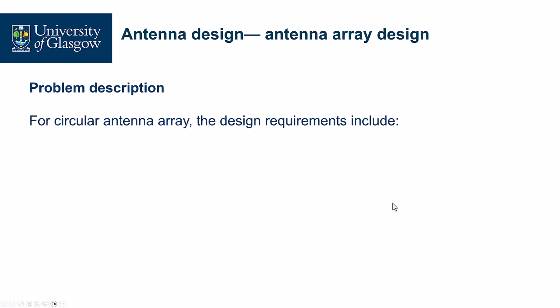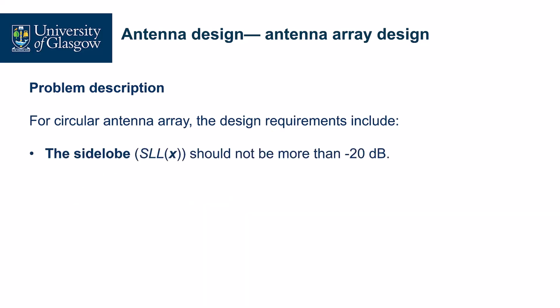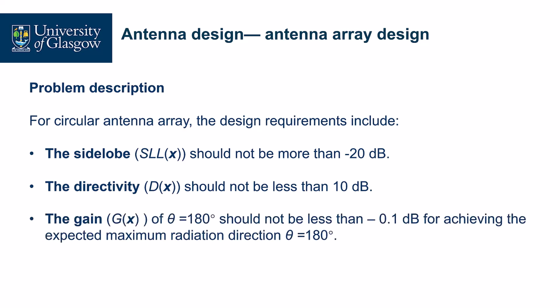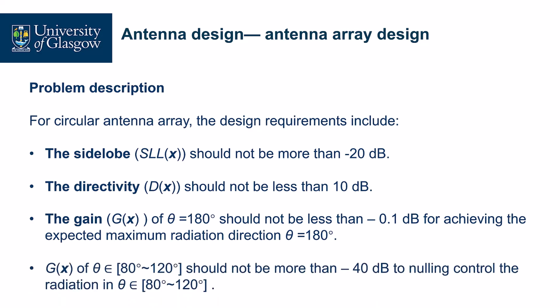When we have the design variables, we need to see the design requirements. Here I listed them as follows. First of all, the side lobe level SLL should be not more than minus 20 dB. Directivity should not be less than 10 dB. The gain at 180 degrees should not be less than minus 0.1 dB. And the gain from 80 degrees to 120 degrees should not be more than minus 40 dB.